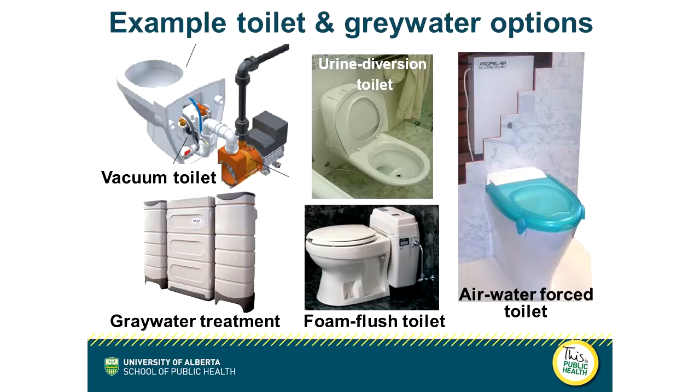And as I said earlier, we can treat grey water, and I'll show you some examples of this, to a quality that is acceptable from a safety point of view, from a pathogen reduction and chemical reduction point of view, that is safe for toilet flushing, is safe for clothes washing, is safe for garden irrigation purposes. And that's about 70% of our water needs. Okay? And we wouldn't have to pump it all the way somewhere, treat it and pump it all the way back again. We could do that on site. Okay. So this is part of the reimagining our water systems.